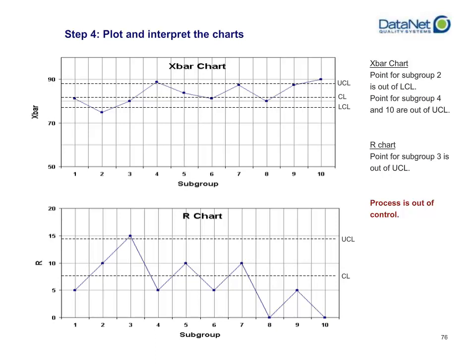But your R chart is also showing some information. With regards to volatility, you're not seeing a whole lot of volatility within the process. However, subgroup number 3, even though subgroup number 2 was in control with regards to the average, the range in that data was 15. It was higher than your upper control limit for your range value. So you may want to see why your process was so volatile. Perhaps your process was changing dramatically.